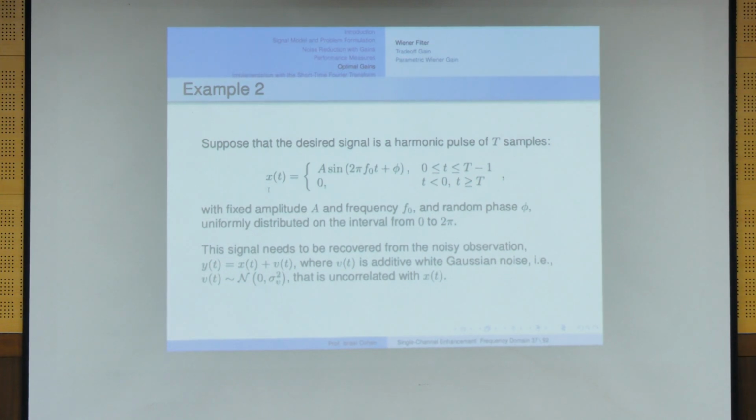We will see that it's not exactly a sinc because we have a certain length, so it's a periodic sinc, which is the Dirichlet function. And then we have the periodic sinc, the Dirichlet function, convolved with a spike or with a constant. So these small details are important when you solve problems or deal with problems. So let's move on.